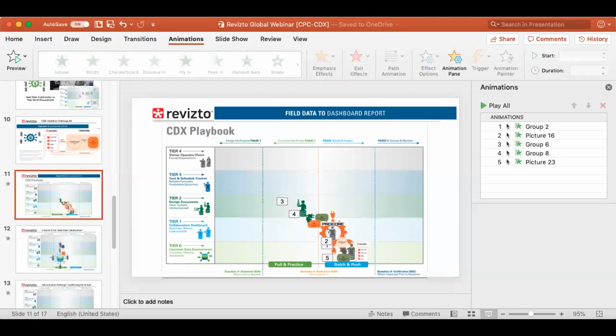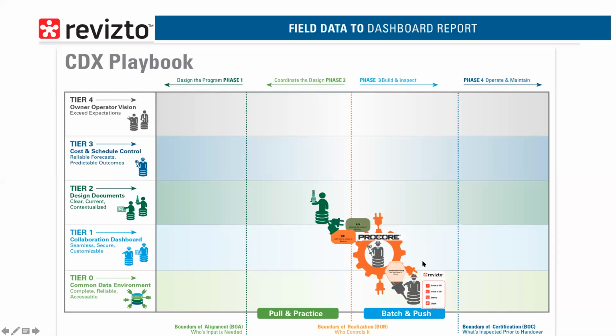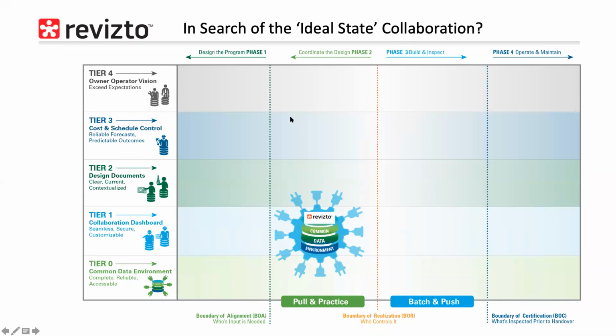Okay, great. So rather than looking at Procore as the central hub of where everything goes through, which is really, I would argue, a private data environment for that general contractor, there's this other approach. If we're much earlier in the phase, being more collaborative inside of BIM, when a coordination issue comes up and is developed in Revizto, the contractor still needs to record that inside their Procore system, or maybe an engineer can provide comments, because it's a free, open, transparent common data environment. But if that does need to become a formal RFI where we need a formal design response, then it can still be elevated, even though it may be contractually inside Procore. Everybody's stayed aware of it and updated within the Revizto common data environment.